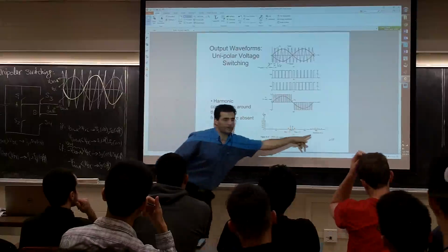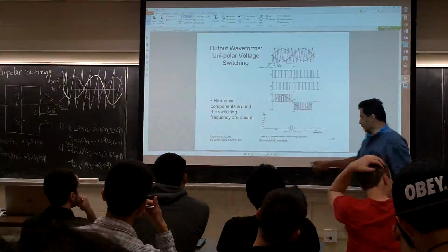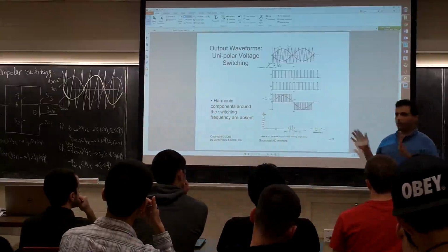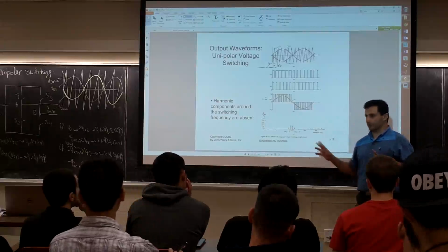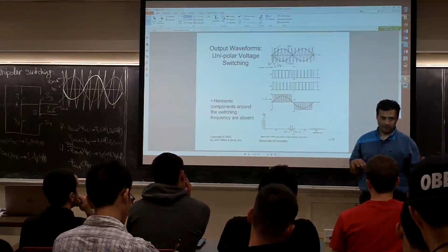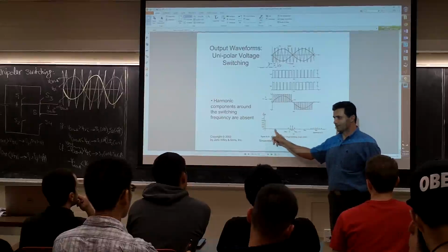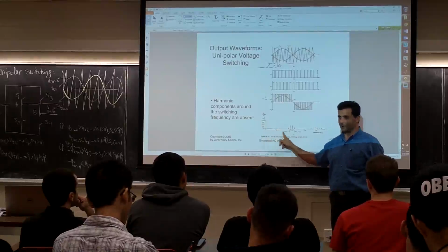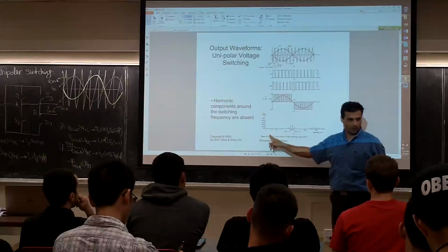Look at the harmonic spectrum here. So this is exactly like what we had for the bipolar, but that one we said is going to be J MF plus minus K, right? And J could be odd or could be even, right? For this one, the odd ones are gone. There is no MF anymore. See, there is nothing here. Previous one we had here, right? We had MF plus minus 2MF plus minus 4MF.